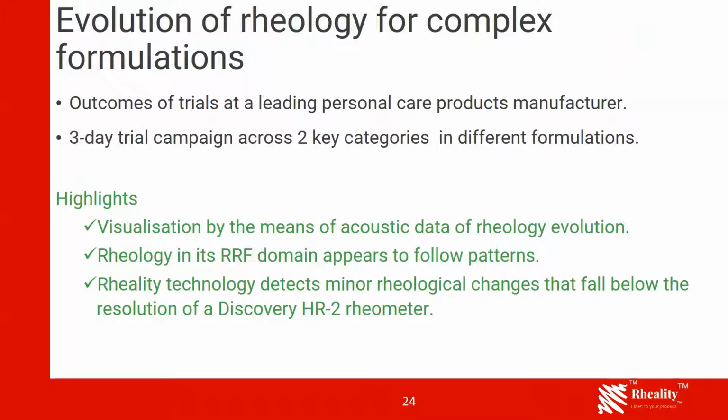What happened as well, and that wasn't our original intention, is we took a comparison between our measurement and the traditional offline rheometer, and we knew there were certain ingredients going in. By the law of nature, those ingredients used would alter the rheology, but a standard offline rheometer was not able to detect rheological changes at those small addition levels, but our technology gave a very, very distinctively different acoustic response to these fluids. That's why we say we are confident to go way below the 0.05% weight percentage changes in ingredient addition, which would be very nice.